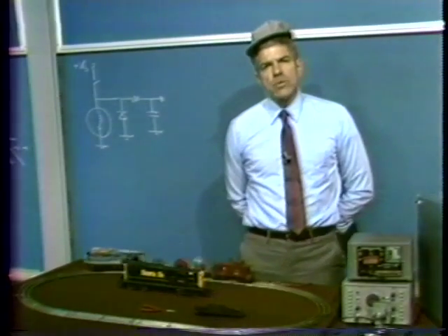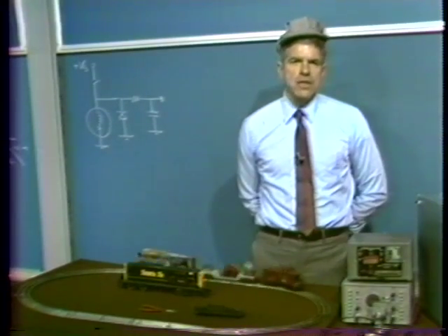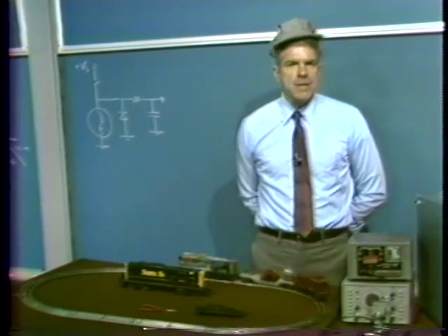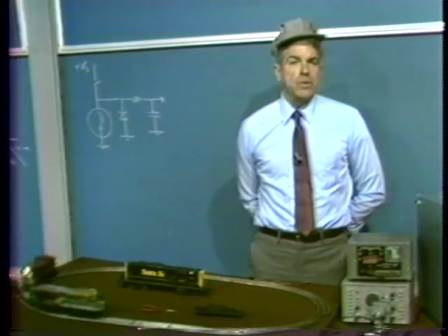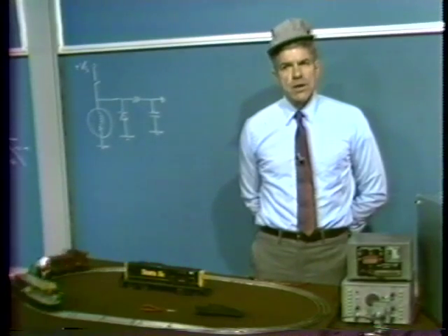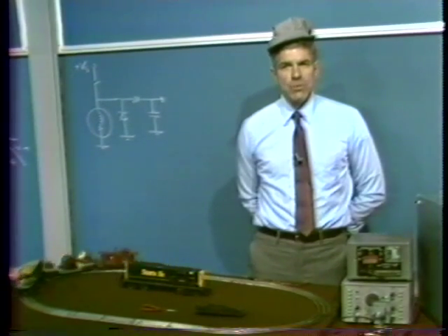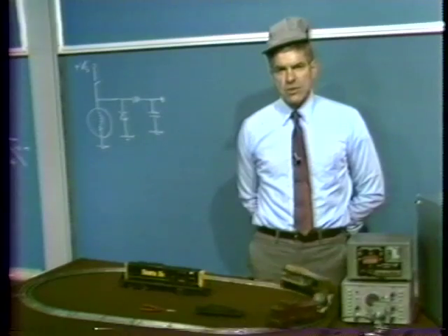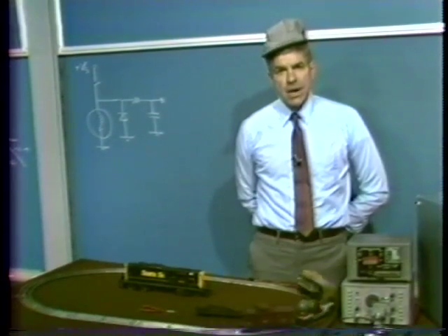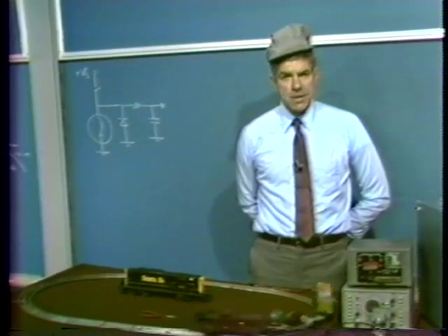There's a question as to how do we do the power amplification. A Lionel motor takes something on the order of 1.5 amps to operate under normal load conditions at maybe 10 volts or thereabouts. So we have to put somewhere between 10 and 20 watts into the motor. Furthermore, again, my grand plan involves running more than one motor per engine. You can really climb the highest mountains and whatnot if you have more than one motor. So I anticipate normally using at least 2 motors per engine or back-to-back diesels, something like that. And I'd like to run them off a common power amplifier. So I have to have a power amplifier that maybe can put out 25 watts or something like that order to power my engines.